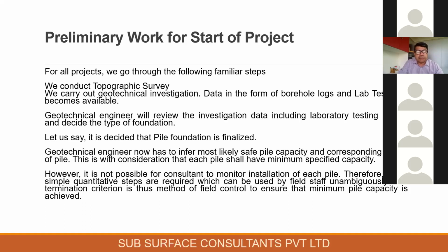That is what we are going to call the pile termination criteria. The pile termination criteria thus becomes the method of field control to ensure that minimum pile capacity is achieved. I am not saying pile length. Please remember this. I am saying minimum pile capacity is achieved.